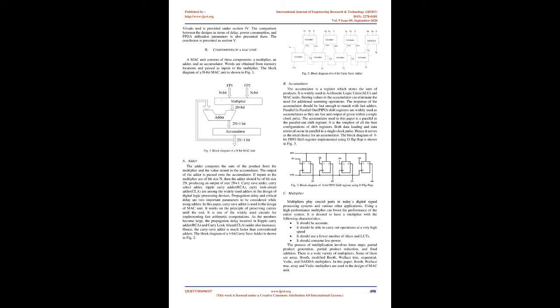In 1, various multiplication hardware realizations have been presented along with a detailed description of parameters to be considered while designing any digital system. A revolutionary multiplication technique for signed binary numbers has been proposed in 2. This technique, widely called Booth's multiplication algorithm, is independent of any foreknowledge about the signs of these numbers. In 3, a MAC unit was designed using the Booth multiplier and ripple carry adder. The MAC unit coded in VHDL was analyzed, synthesized, and simulated using the Xilinx ISE design suite.